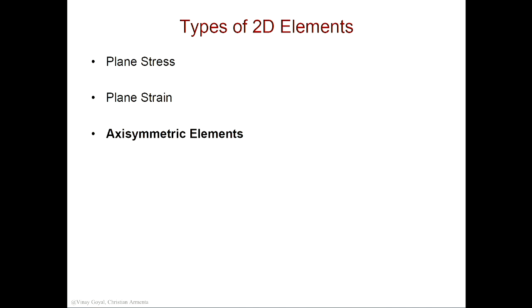So we discussed plane stress modeling, plane strain modeling. These are 2D elements. We discussed that. And plane stress typically is thin, like a thin plate, but all the loading is in plane to that plate. Plane strain will be, for example, a long tube, and every cross-section is the same as other cross-sections throughout the thickness, but you're looking at very long structures.